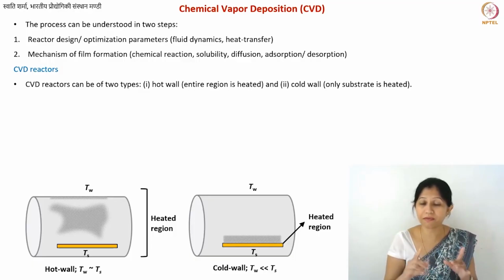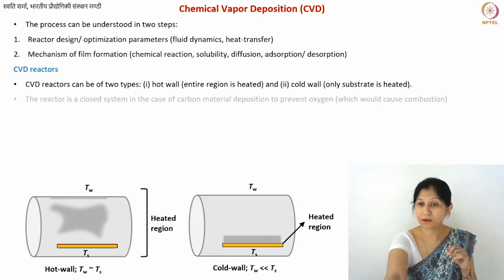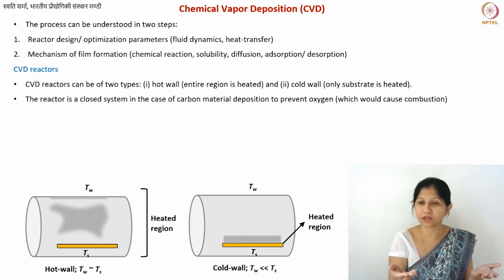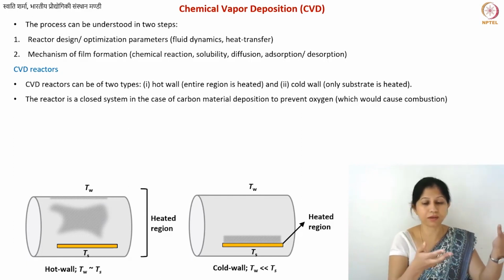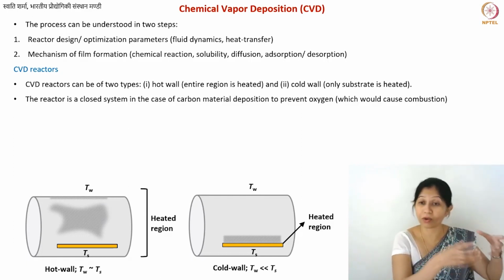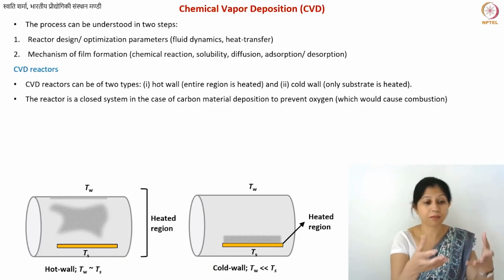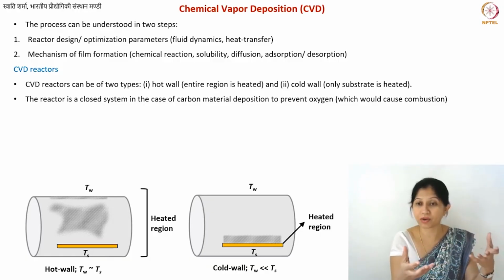So one more very, very important parameter inside all the CVD chambers: you must have a laminar flow and not a turbulent flow, because you want to get a film deposition, right? With turbulent flow, at some locations you will have a lot of deposition, then some locations will not have any deposition, and so on. So you definitely do not want a turbulent flow.